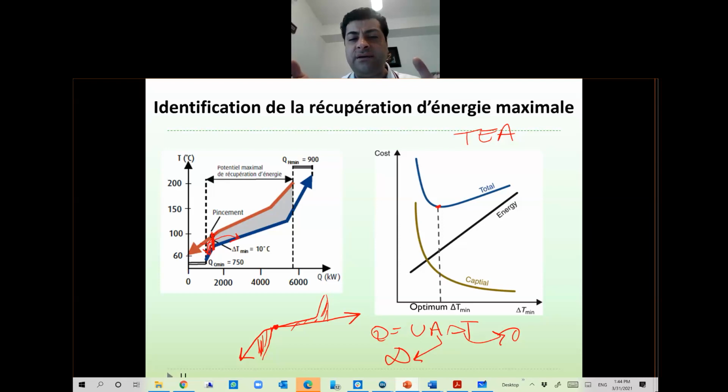But anyway, this technique of pinch analysis is extremely important in order to maximize the overlap between the process streams, so you can maximize the total cost optimization and minimize the utility consumption, minimize consumption of cooling water, and electricity if you are using, for example, an electrical heater or boiler, whatever, in the utility part.